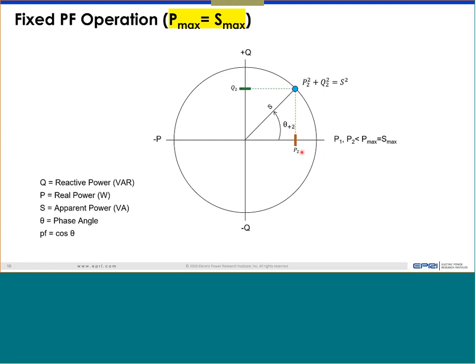So that also matters: if you're operating at lower output already, of course you can operate in this mode without any curtailment. The curtailment question comes only when you have the potential to generate full or high power, and then because of the power factor setting, you have to reduce it. So one of the fundamental questions is how the inverter is designed. That's number one, and I'm giving another example.